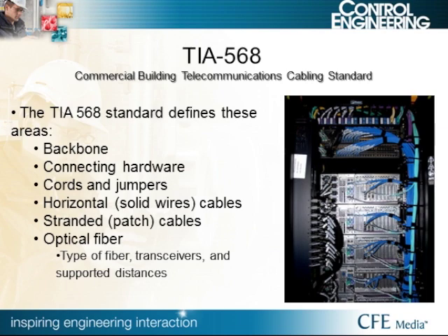When they talk about media, they talk about both copper and fiber media. The cords and jumpers are also defined, and it is stressed that the patch cables be of the same or better category than the backbone cable. In other words, if you installed Cat 6a cable, make sure that you use Cat 6a patch cables to go with it.